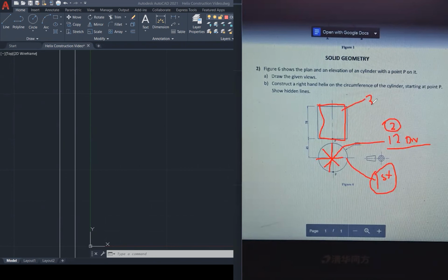That's the third thing I'm going to draw. Okay, after drawing all three of those things, I'm then going to divide the rectangle also into 12. So I'm going to type divide, div 12, all right? So that's four things I'm going to do so far. Once I've gotten to this stage, then I'll discuss the other things that I'll be proceeding to do next.